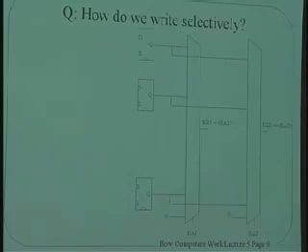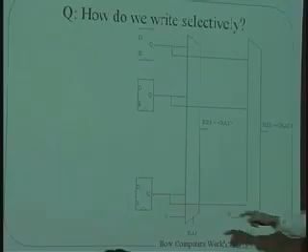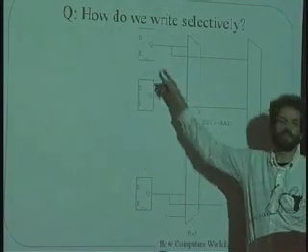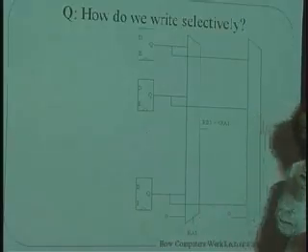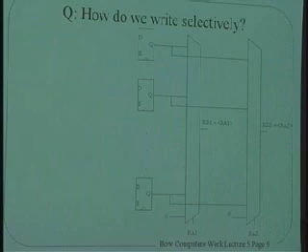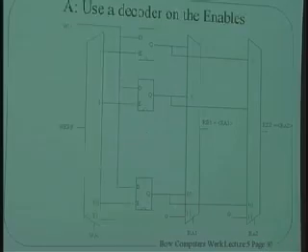I could put a bunch of AND gates with the clocks, saying depending on which of the registers I wanted to write, I'm either going to trigger this clock or trigger this clock or trigger this clock. Change which shutter gets the finger to press on it. But it turns out, and we'll see reasons later for why this is true, that trying to gate clocks, trying to control which shutter is pressed, is actually very hard to do. And it's actually easier, and you get much more time to get the job done, to disable certain of the cameras and only enable one of them so that all the shutters are pressed at the same time, but only one of them works. And let's take a look at how that works.